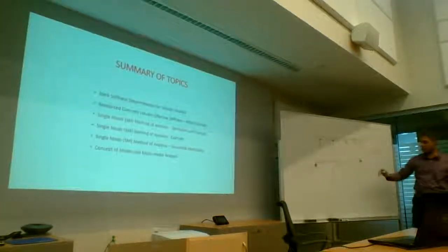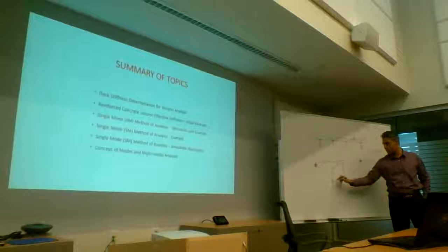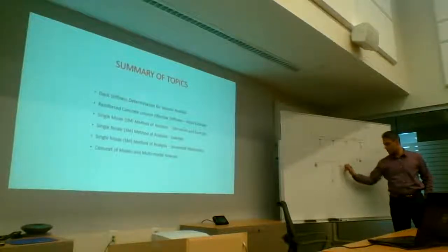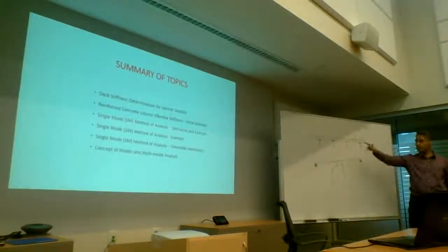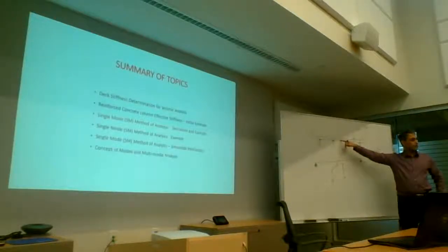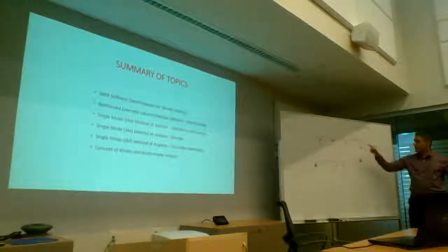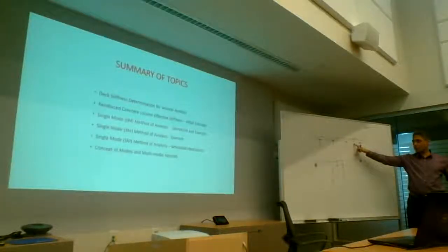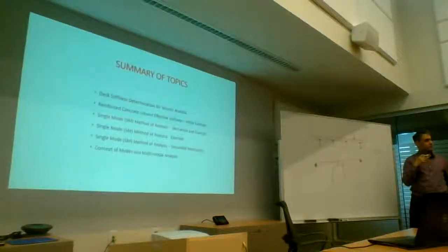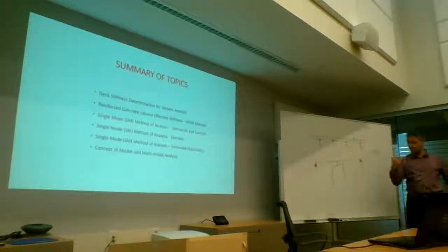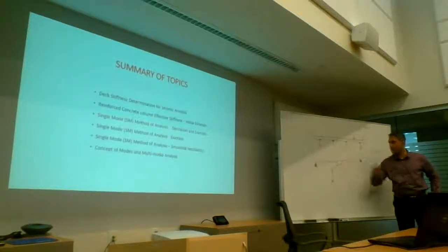Because seismically, we've already discussed, your load is into this bent. That's the critical element, not the deck. However, the load is generated due to the deck. It's the mass of the deck and the CG of the deck plus the stiffness of the deck that drive the generation of the seismic load. The resistance comes from this.